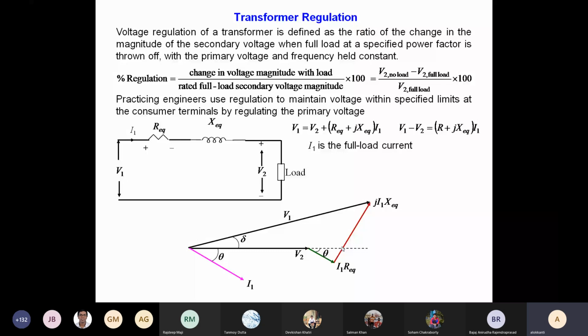Okay, so the V1, the supplier, cannot give an infinite amount of voltage. Then what will actually happen is that the V2, that is at the customer end, will keep on falling. If you draw more and more current, if your I1 is increasing, and the power supply company has some calculations, but more than that is being drawn, then it will lead to a drop in V2, because beyond a certain limit V1 cannot also be operated. Okay, so does it answer your question?